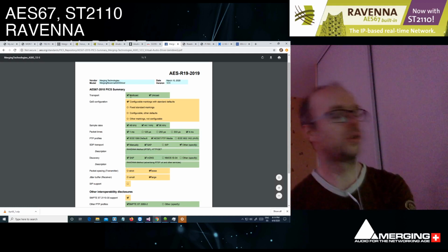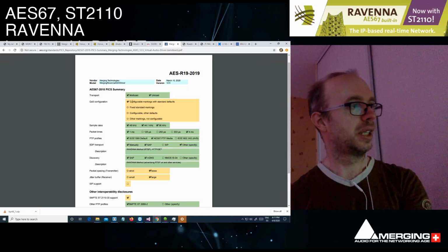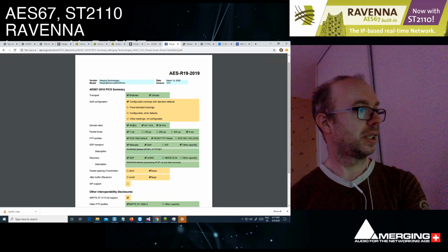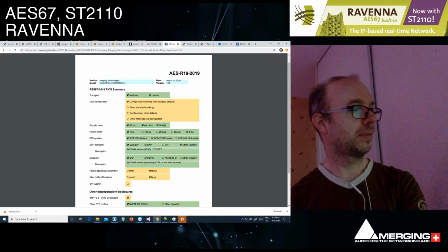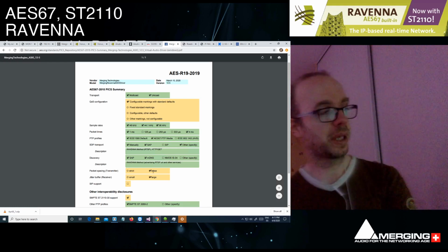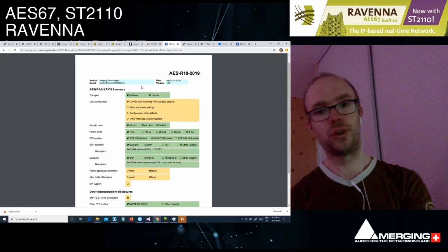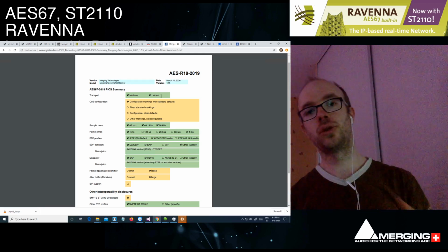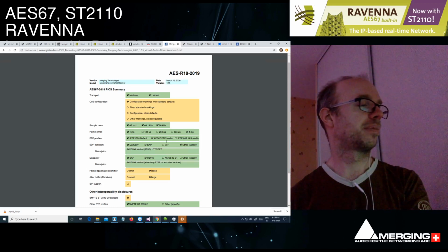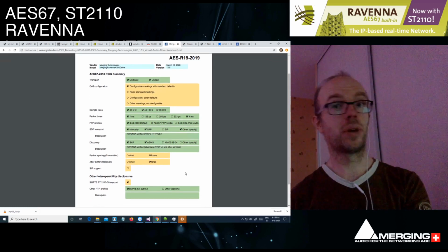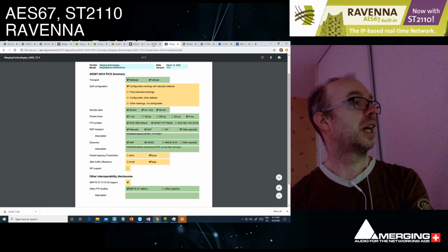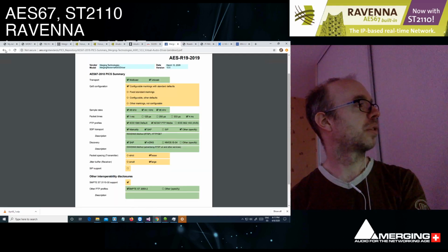And so we can see that the ASIO is capable of doing Multicast and Unicast. That is, the QoS is fully configurable, that the sample rates can go up to 96 kilohertz, etc. That it can do SAP, mDNS, that it has a loose packet transmit time. This is because it's the ASIO driver, so it's a software driver. So the time between the packets, even though it should be exactly 1 millisecond, for instance, it cannot be exactly 1 millisecond because the software is limited by the power of the computer, the jitter buffer that is large, and the ST2110-30 compatible, etc.